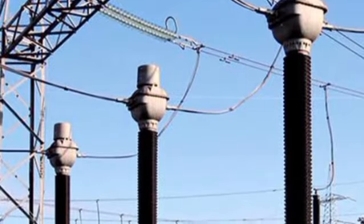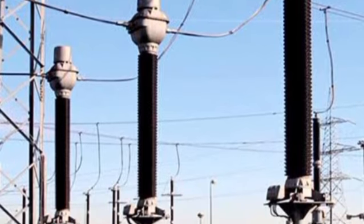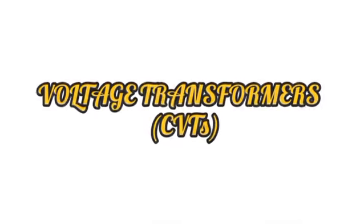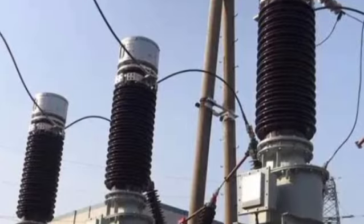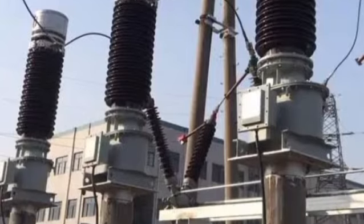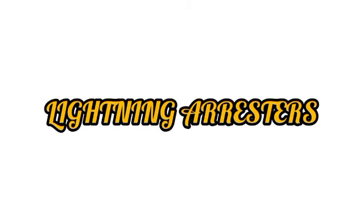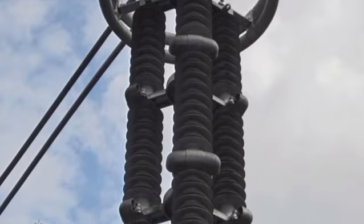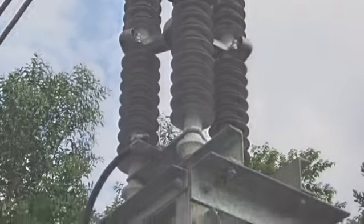Function: provides scaled-down current signals for metering and protection, typical ratio 1200/1A, 1500/1A. Voltage transformers, CVTs. Step down high voltage for protective relays and meters, and can also serve as carrier signal coupling devices in communication systems. Lightning arresters. Protect equipment from lightning strikes and switching surges, installed at line entries and near transformers.